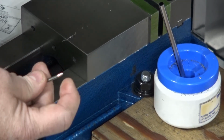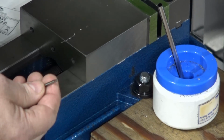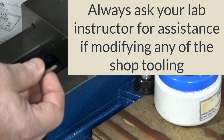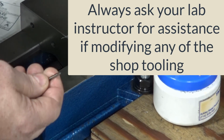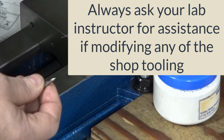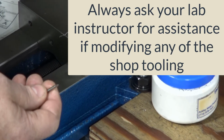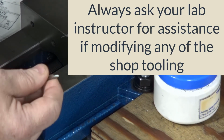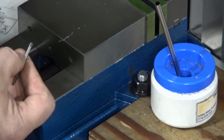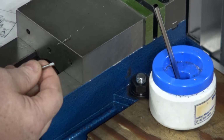Now, if the tip of that tap is going to give us any issues, we can just grind that off of there. There's nothing on that tip that the tap actually needs to generate that thread. That's actually there during the manufacturing process of the tap. And the only reason they don't take it off at the factory is because it takes more time, which would cost us more money.